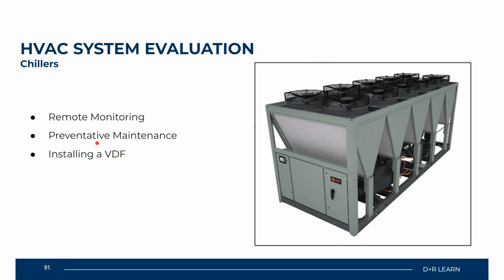Your chiller system, you want to make sure you absolutely have your remote monitoring working, so all sensors are operational and don't have any flaws or faults. You want to make sure your coil is clean, compressors and refrigerant pressures are up to date, and you might want to think about installing some sort of a VFD system on your chiller application, whether that be your pumping system or your compressor system, so that you have that system running extremely efficiently.